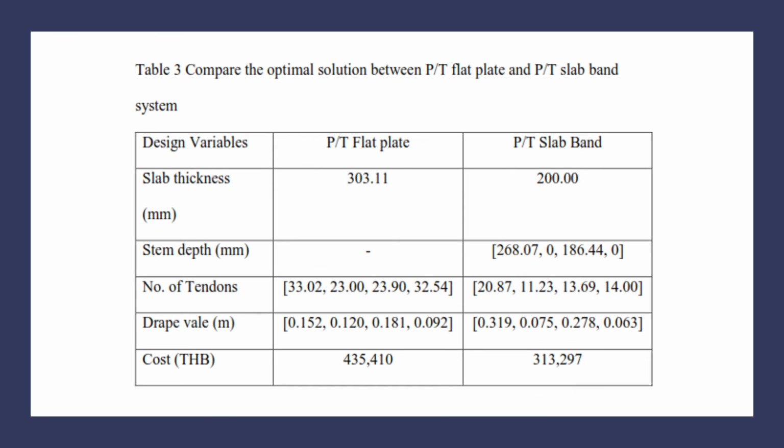This table compares the optimal solution between post-tension flat plate and post-tension slab band system. It is obviously seen that when including slab band as another design variable, it is possible to get a better design solution, in other words, the cheaper design.